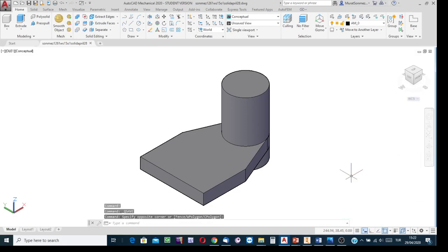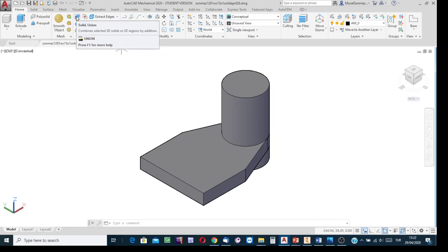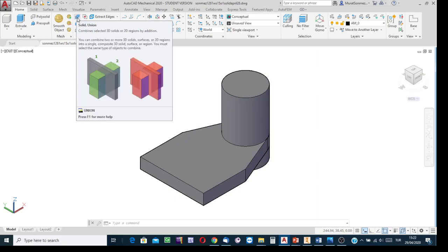Continue. Well, here after having the cylinder and this part, by the way, you know, in AutoCAD, created features are considered as if components. This prismatic part and the cylindrical features are not unified yet. Either at that stage say that these are not different objects but the features of the same object. Apply Boolean algebra. Using Boolean algebra, unify them.